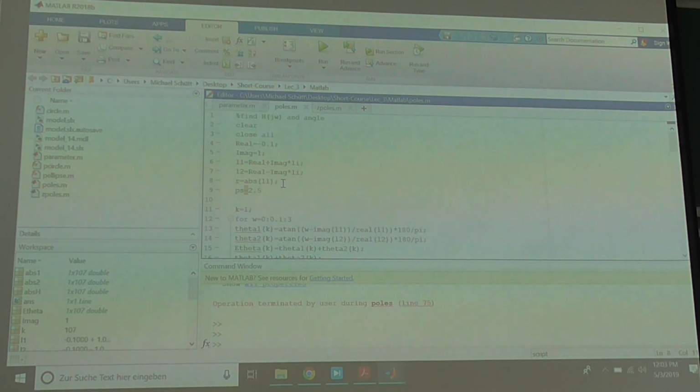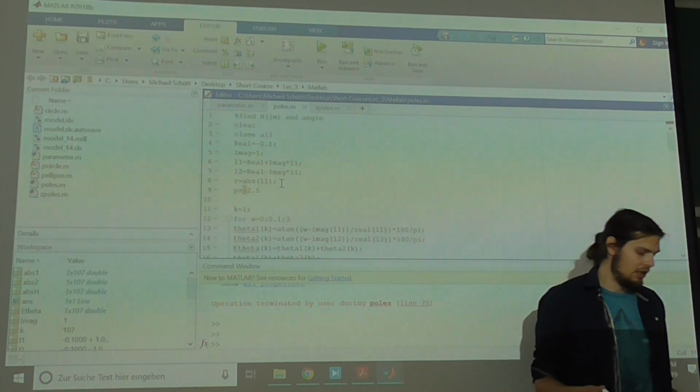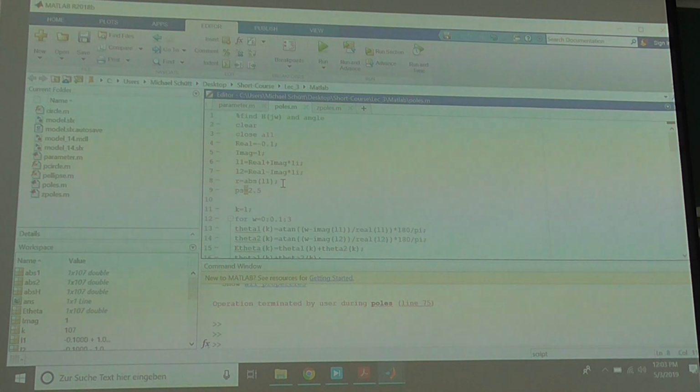So when we do these plots of command tracking and dynamic stiffness, we have to also think about robustness, right? If you think about feed forward or decoupling, they only work as good as your parameters are. Okay. So, if we look at these, which one do you think is the most important when we think about modeling and building our state feedback controller?